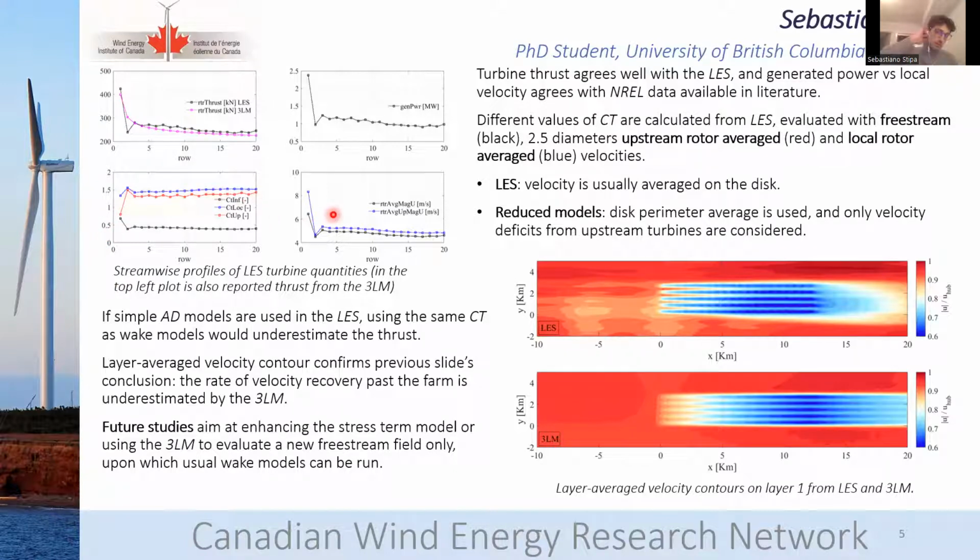And usually what can be done is to use the induction curves, the induction coefficient, to compute a kind of free stream average based on the rotor disc. So basically you have the velocity of the rotor disc and you use the induction to compute a hypothetical free stream velocity with which you dimensionalize the CT coefficient.